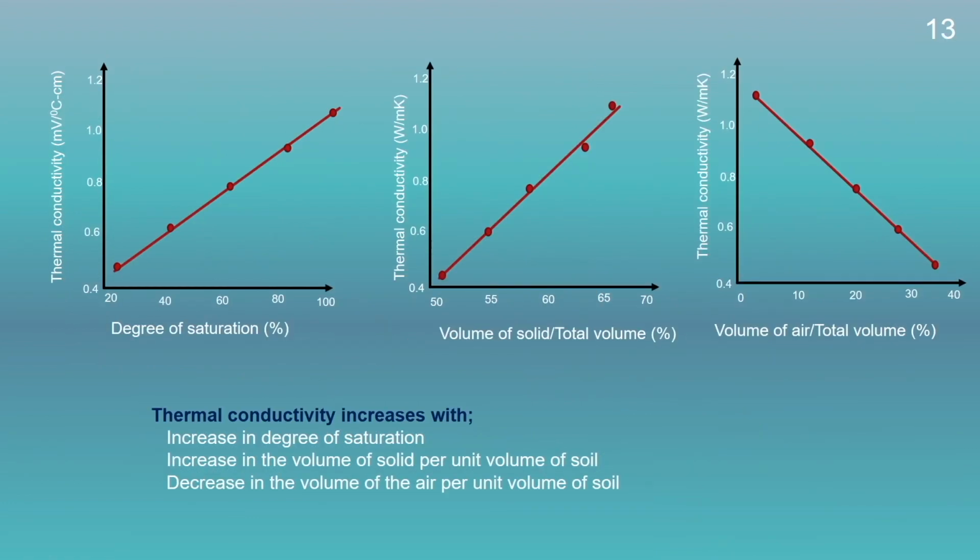In this plot, the relationship between the thermal conductivity and degree of saturation has been shown. As expected, with increase in the degree of saturation, the thermal conductivity will increase. With increase in the degree of saturation, more amount of water will be present inside the void space. As more water is present inside the void space, more heat can transfer because of the convection phenomenon. Therefore, with increase in the degree of saturation, the thermal conductivity will increase.